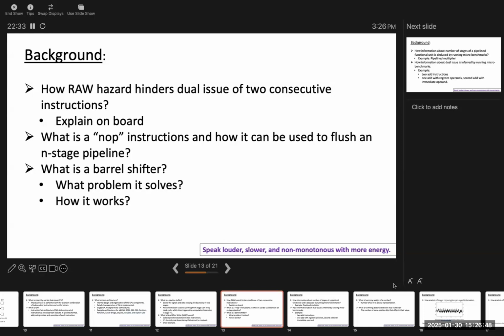Now consider that my register is not 4-bit. My register is 64-bit, okay? And I want to shift the data by 8 positions towards the left, or 16 positions. So how many cycles will it take? 8 cycles or 16 cycles, depending upon the amount of shift you want to perform, which becomes expensive, right?